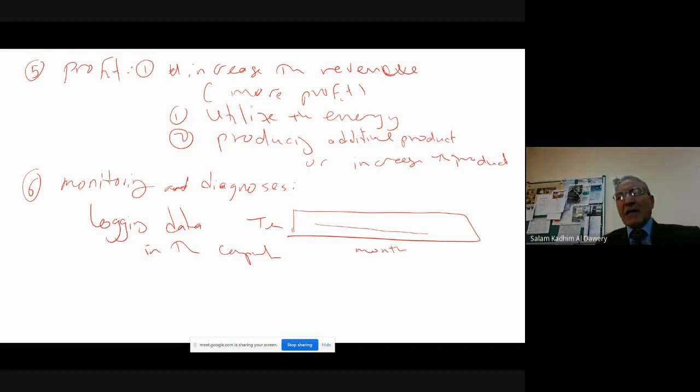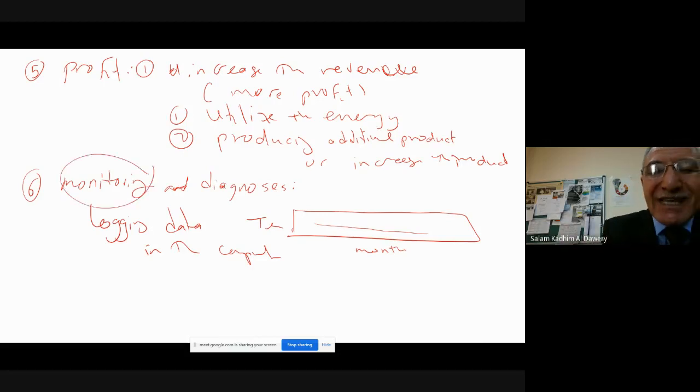So that's how we know. We need something. If things are recorded, we can look: is it drifting? We can look at when there is fouling, for example. That's for temperature. If the pressure rises, that guarantees it's a fouling issue. But if the pressure is not rising due to a blockage in the pipe, it means something else. We have to study why for that particular period.